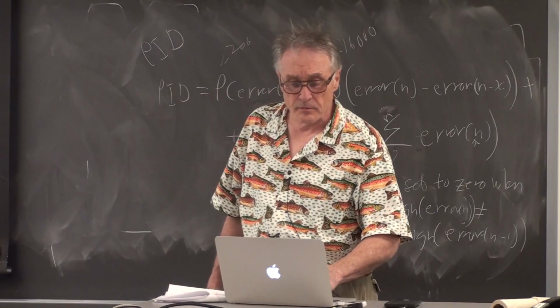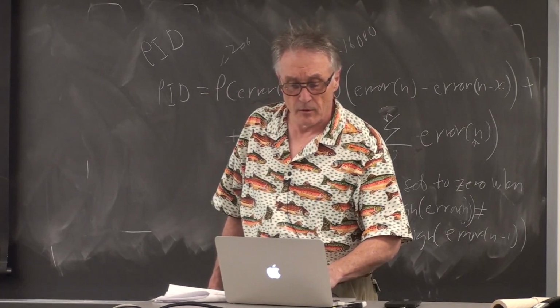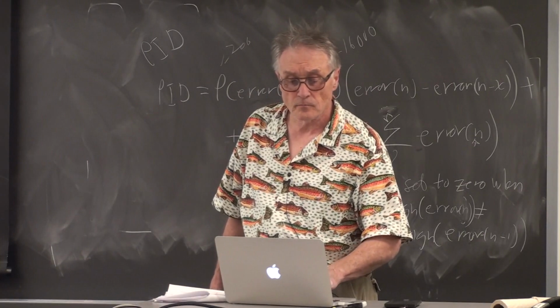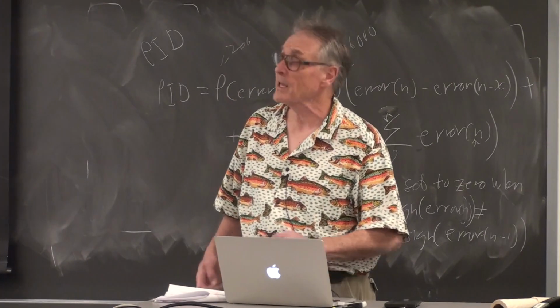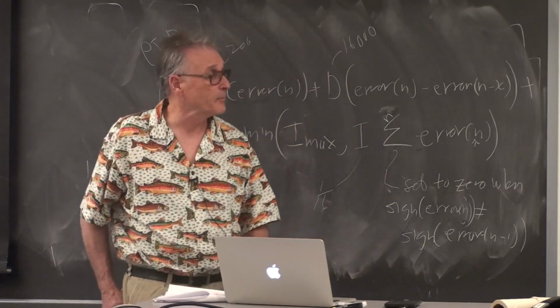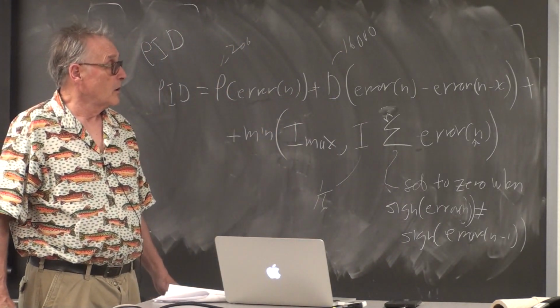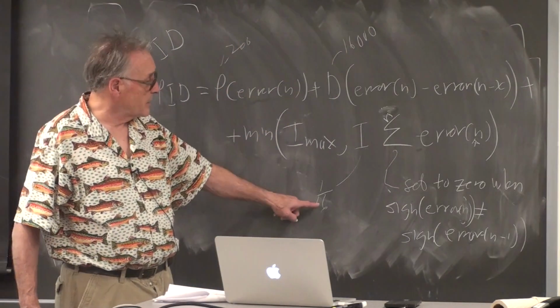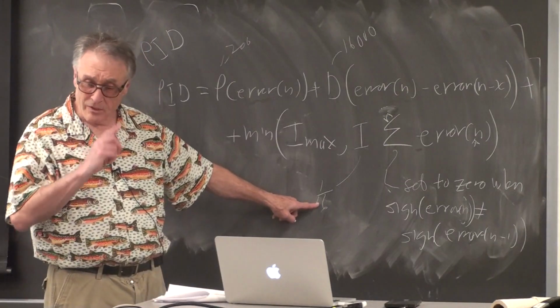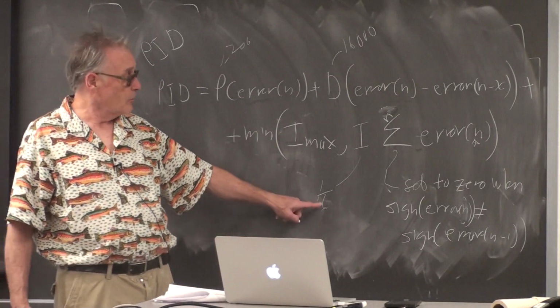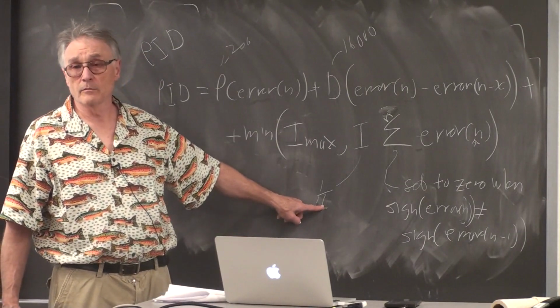Turns out this particular response is not the most stable. But the MATLAB is pretty closely tuned to optimal. I was playing with KI this morning. KI 1/16 is stable, 1/2 is stable, 0.75 is unstable.